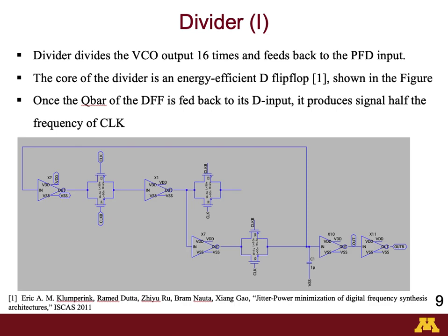So it's very important to note that the choice of the D flip-flops is important since it may be a vital component in the overall power consumption of the system. This rigorous analysis of power consumption by different sorts of D flip-flops has been done by Professor Eric Klumperink in this reference, which was published in ISCAS 2011.